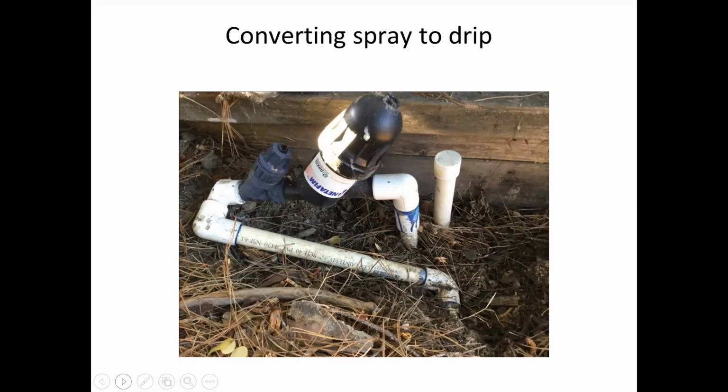And don't forget, at the beginning of the valve, you want to make sure that there is a pressure regulator and a filter. So those are just the simple, little component tweaks that you can make to what you already have existing to make something more appropriate.